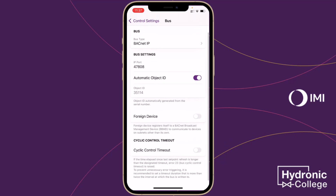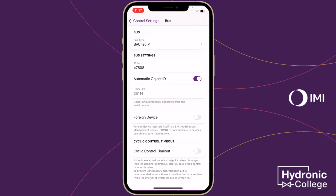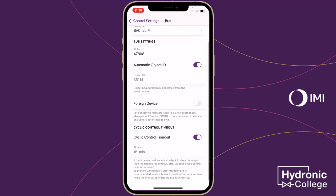To enable control fallback, cyclic control timeout must be enabled. The cyclic control timeout is the period after which the TA Smart will raise error 23 if it has not received a refresh of set point. It is recommended that this interval is set to over 2 times the interval to which the bus is written to in order to prevent unnecessary error triggering.